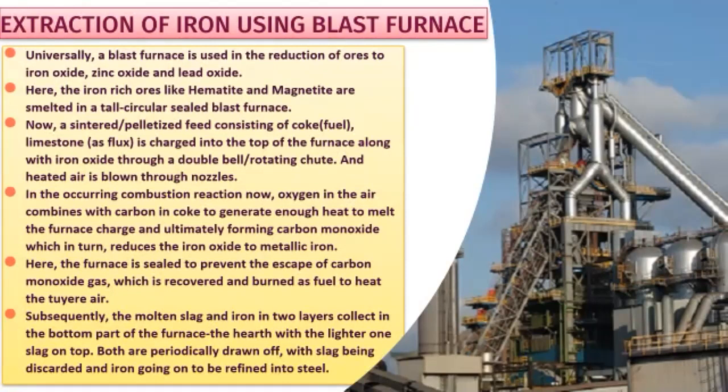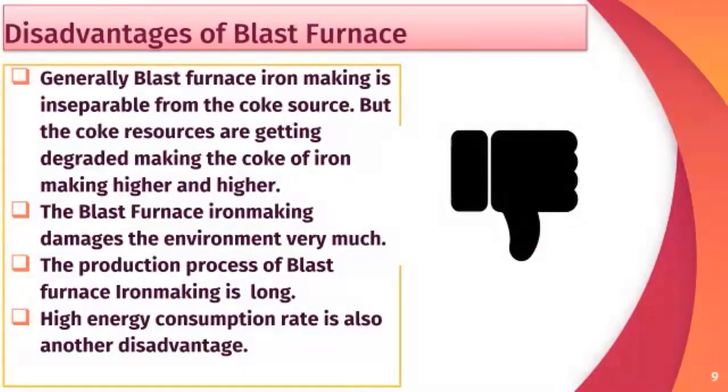Although blast furnaces have been in use since many centuries, there are ample disadvantages associated with them. And the disadvantages are as follows. That is, the extensive requirement of coke in the blast furnace makes the natural resources of coke depleted. Then there are environmental concerns in the form of pollution. And this process is also a long one, which consumes high amounts of energy, resulting in lesser yield.